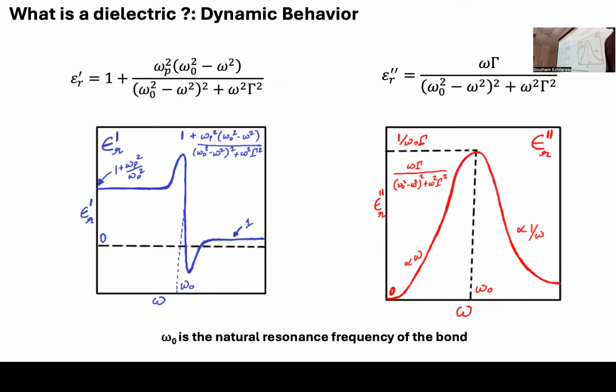And so, the main thing is if you plot the real part and the imaginary part of the dielectric constant, right? What you notice is that epsilon r, the real part of the dielectric constant, which is the actual dielectric constant that you talk about when you talk about high K and low K, remains constant up to a certain frequency, but beyond some point it starts falling.